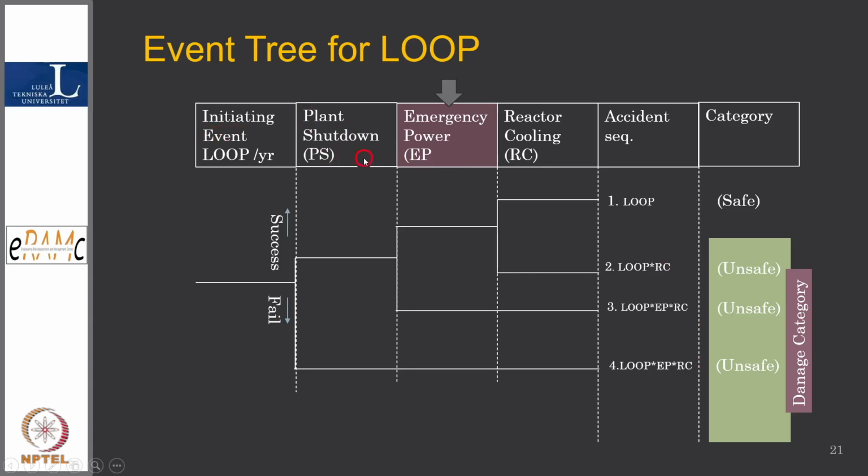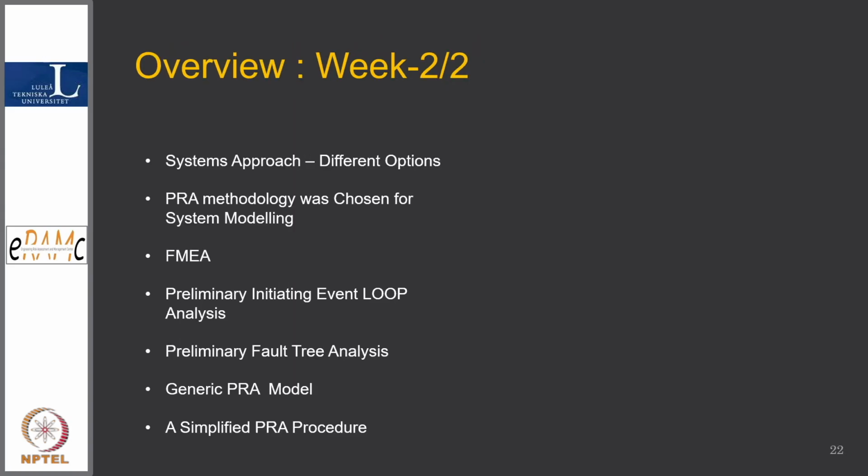And for these three frequencies, the way I have done it for loop, if I analyze the fault tree and have the quantification, I can quantify these, and adding these three accident sequence frequencies, these are called accident sequences, I will get the damage frequency for the plant. So what an elegant framework. I have given you a very simplistic perspective of a plant, but it is sufficient for you to understand what the plant means actually.